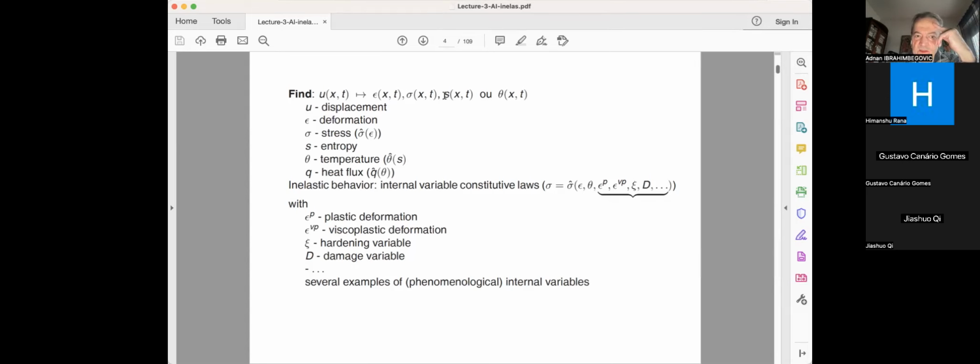Heat flux, you will see by Fourier's law, is in the opposite direction of the temperature gradient, as opposed to stress, which is in the direction of the displacement gradient, which is the strain. So there's a minus sign. And that is actually a physical observation: if you put a radiator in the corner of your room, the room gets heated, because heat goes from something hot to something cold, as opposed to the gradient, which goes from something cold to something hot. And that's why you can heat.